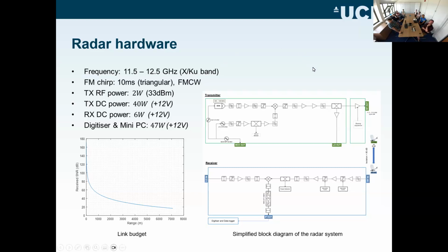Just going through the design itself, the transmit radar obviously starts with a source of a linear chirp, which is produced by synthesizers, so a DDS. We produce a chirp from 400 to 1400 megahertz. We're using the fundamental signal of the DDS, which gets converted into an IF signal that gets conditioned. Then we're using a superhet architecture to directly up-convert that, and in fact, we high-side inject that LO. The RF again gets conditioned, pre-amplified, and transmitted through a 2 watt amplifier. A replica or copy of that signal is then tapped off and shared with the receive side to produce the intermediate frequency, as you would do with FMCW radars.